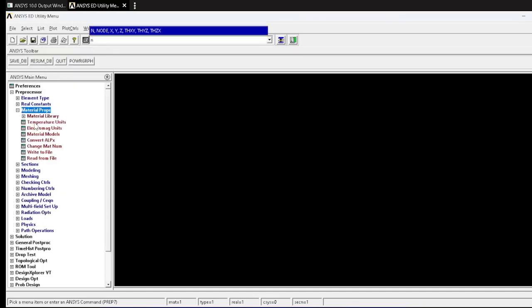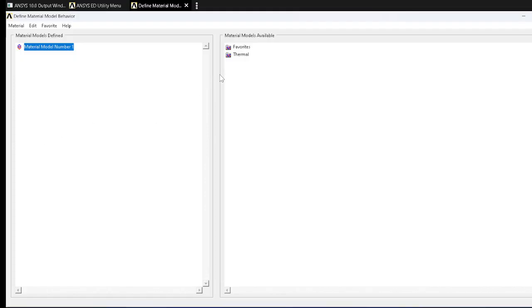Now we need to select the material models. This is very important. We have three different materials, so three different properties. Therefore we need to create three conduction-type properties along with the convection. So totally there are four material models we need to create. For that, under thermal, you have to click conductivity. Because we selected a thermal problem, unlike the previous structural one where we got isotropic linear elastic Young's modulus, now we need to give thermal properties. Conductivity is a thermal property.